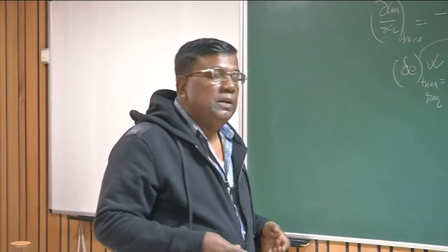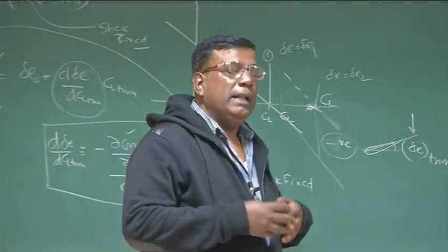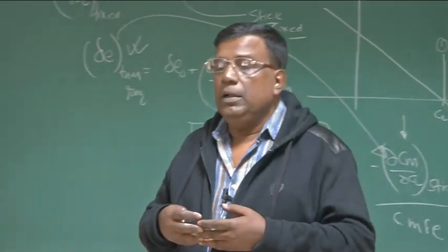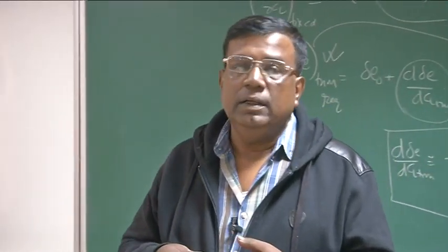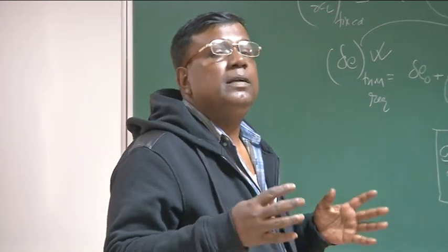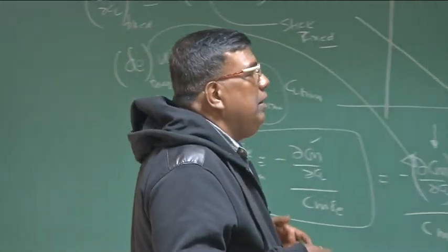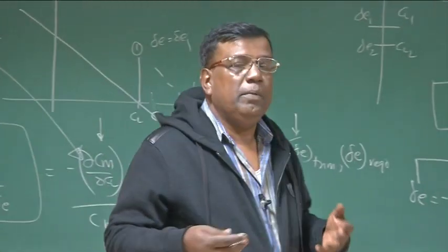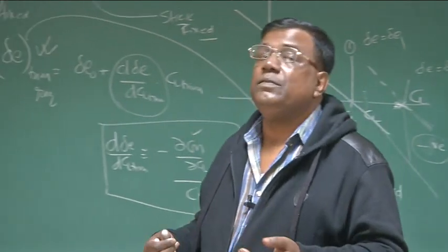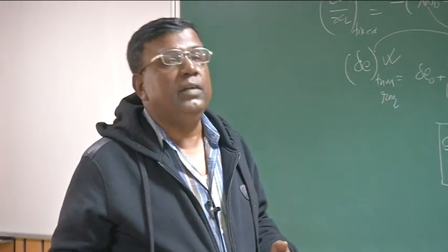To develop an expression so that we can quantify, we can develop a mathematical model to give a feel for the pilot, and there we are using the concept of stick-free stability. I repeat again, only to develop a mathematical model to give a feel for the pilot, we are talking about stick-free stability, or we are building the concept of floating of the elevator.